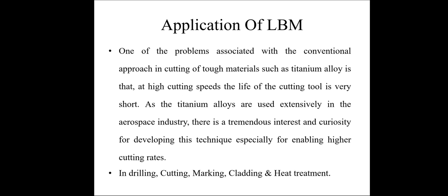In drilling, drilling of micro-size holes in difficult to machine refractory material is the biggest area of the laser application. It is also used in cutting holes and slots larger than 1.25 mm. It is also used for marking, and it is achieved by producing a series of overlapping blind holes that produce a uniform smooth bottom groove.